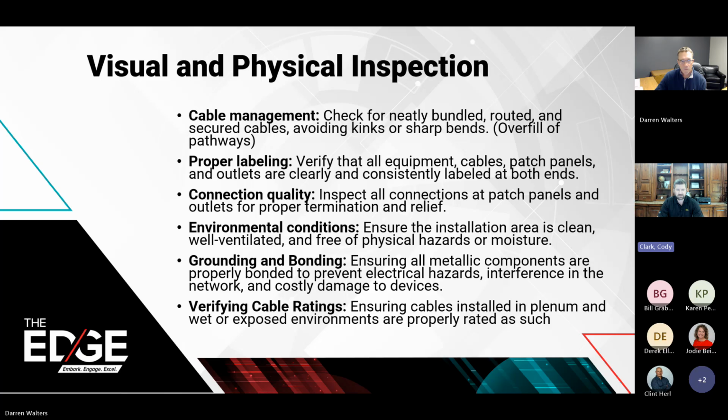Connection quality, inspecting all the connections. This is somewhere where you can catch an issue before it arises. If you notice that they're not properly supported being attached to the back of the patch panel, those cables are under stress over time, that's going to possibly cause you a disconnection or a network drop, which can be very costly and time consuming. Environmental conditions, this is a big one, making sure that you don't have physical hazards or moisture around that critical equipment and systems, making sure it's well ventilated, keeping the area clean.